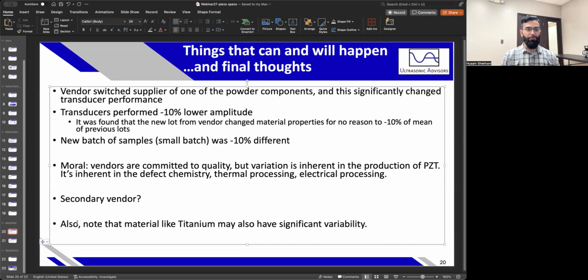you're concerned about. Especially a material like titanium can have significant variability based on many things, including your vendor of titanium, for the same brand and the same composition or specification, for different sizes or different bulk material geometries that you may get, like different rod stock you machine it out of initially, and how that is manufactured. Even if it's the same composition, titanium has a lot of variability. So it's not just piezo ceramics, but with piezo ceramics, we're super dialed in on the variability